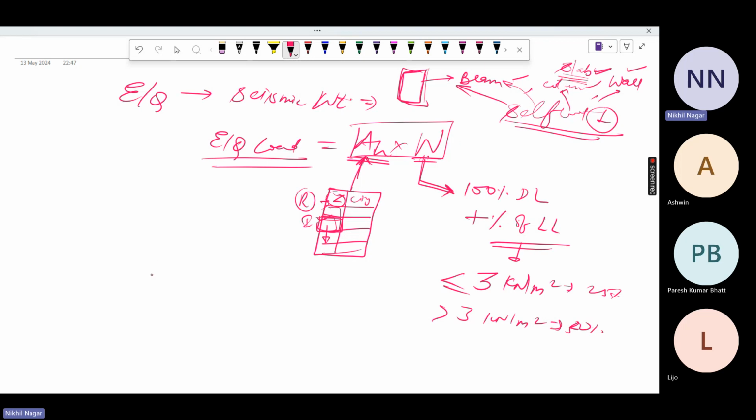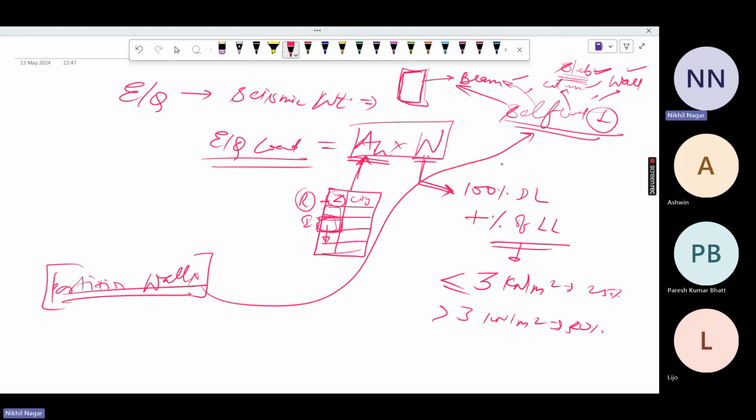Now the remaining things are the partition wall loads. Those are also available in your structure as a dead load, but they will not be considered in your self weight, because the self weight can be assigned only to the member types that your program can see. So you have to assign it manually in the next portion, with some percentage of the live load that will become part of our floor weight.